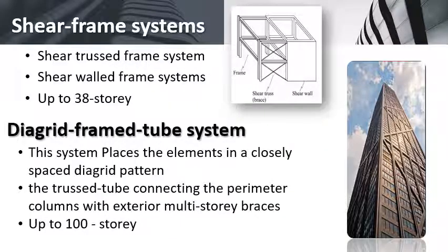The rigid frame system economically doesn't have sufficient resistance against lateral load in buildings over 25 stories because of large deformation. In this case, the total stiffness, and so the economical height of the building, can be increased by adding vertical shear truss or wall to the rigid frame to carry the external shear induced by lateral load.